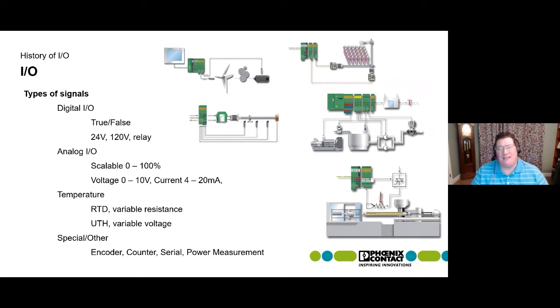And what happens on these sensors is they send a voltage. So when the sensor is true, a 24-volt signal is present. That signal is then read as an I/O point, and then we need to get that information back to our controller to create some type of logic behind that.